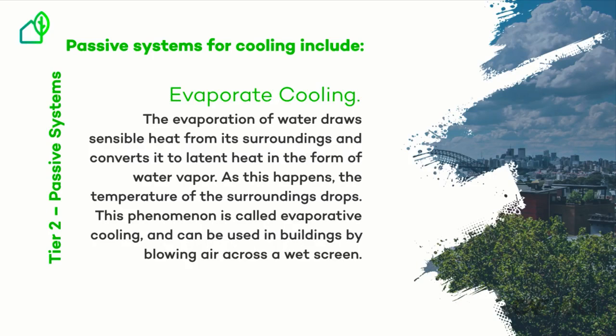While the resultant increase in humidity can be desirable in hot and dry climates, indirect evaporative cooling is better in hot and humid climates where humidity levels are already very high. In indirect evaporative cooling, heat exchangers are used so that no moisture is added to the air.